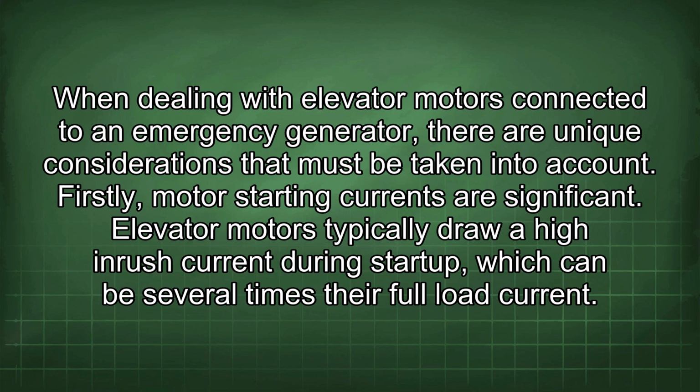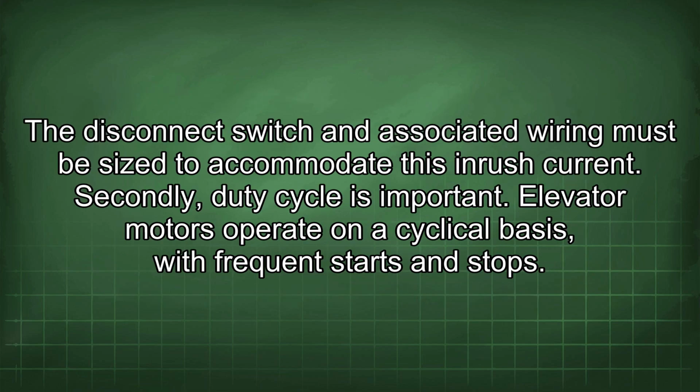When dealing with elevator motors connected to an emergency generator, there are unique considerations that must be taken into account. Firstly, motor starting currents are significant. Elevator motors typically draw a high inrush current during startup, which can be several times their full load current. The disconnect switch and associated wiring must be sized to accommodate this inrush current.